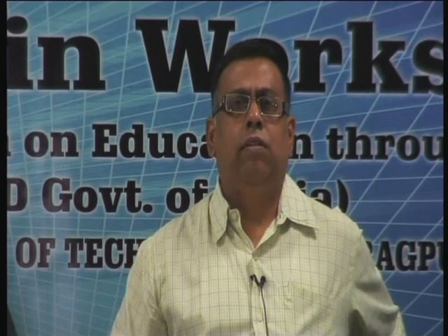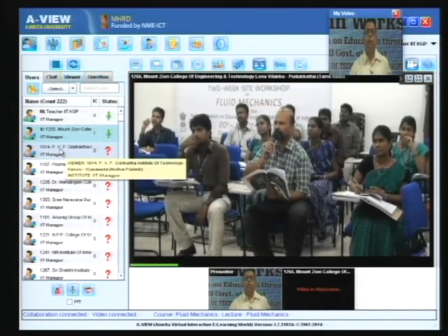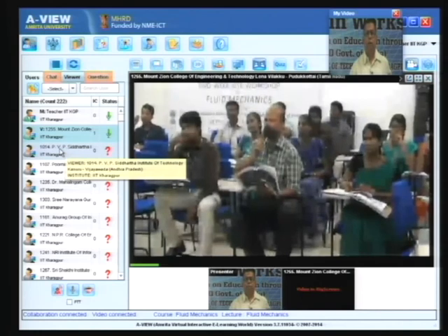It is for measurement of pressure, and as I discussed, it gives you better accuracy, because by making it inclined, you are increasing the reading of the manometer, that is the distance by which the fluid rises in that column. Now, suppose you are measuring it by a simple scale, the least count will be about 1 millimeter. Your measurement cannot be more accurate than that. So, there is always an error or uncertainty of about 1 millimeter.